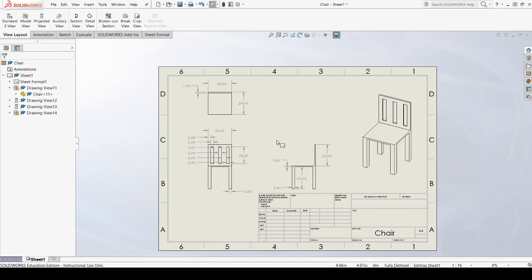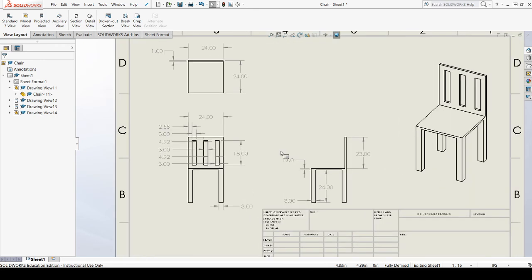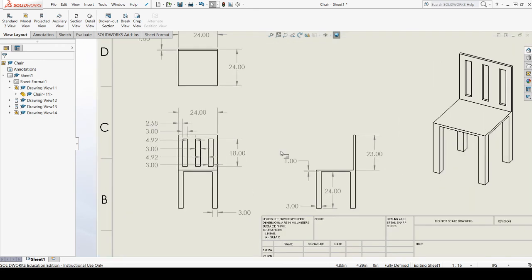Now, something that we haven't talked about yet is tolerancing. So tolerancing is super, super, super important in engineering. Basically what tolerancing means is deciding how good is good enough. So, for example, if you've been in my engineering class, your tolerances are probably like a 1/4 inch. If it's within a 1/4 inch, you're probably calling it good. But for some things, it's really, really important to have close tolerances.